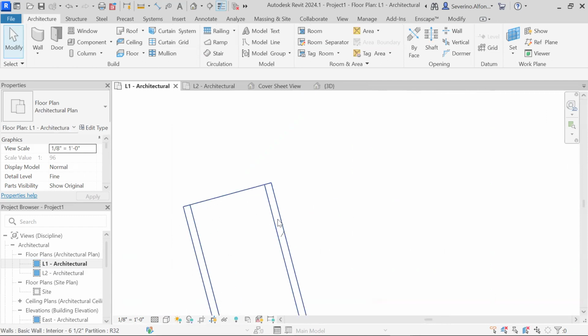You can see those lines versus coarse, where you don't get those lines. What does that mean? Revit has this capacity to show more or less detailed information about an object. In this case, for example, the partitions under coarse view don't have the layers that make that partition. But under medium and fine, you do get the layers.